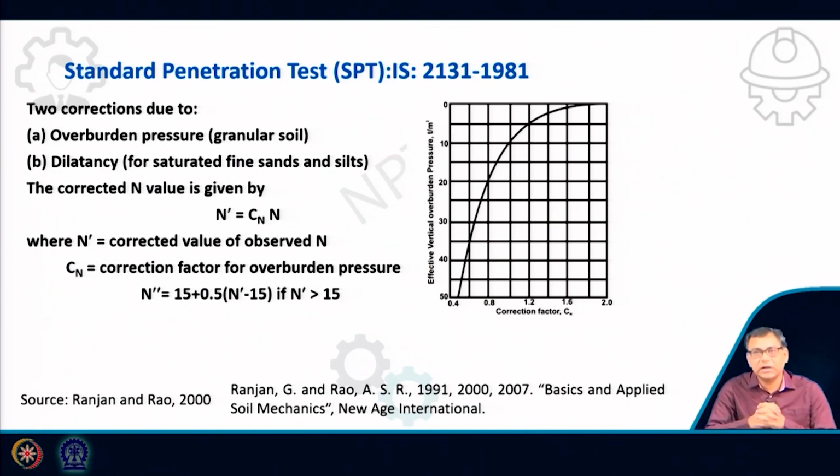But now the question is why we will not apply these things directly. When we apply the load in the real structure, dilatancy may also occur. But the condition is that when we actually do this SPT test, it is under undrained condition. Undrained condition means water will not get enough time to dissipate, so pore water pressure will generate. But below a real foundation, the soil will be under drained condition.